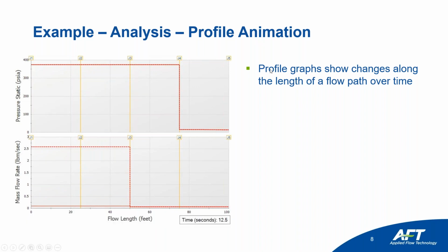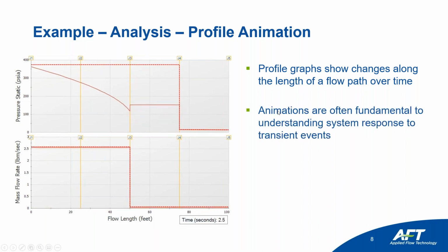So again, profile graphs show any changes along the length of the flow path, any of those same parameters that we were looking at. And it's often fundamental to understanding your system response. So if you get some kind of weird results, usually I would start here, and that will give you some insight into, oh, I didn't anticipate those things interacting, or this valve opened when it should have been closing, things like that.